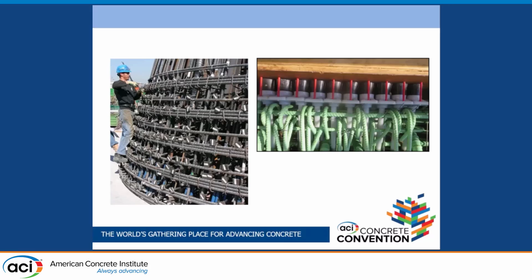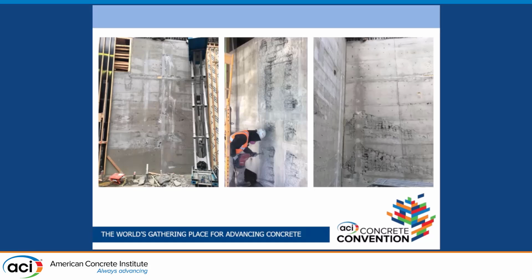Look at that. How are you going to deal with that amount of rebar congestion there? How are you going to place concrete here? This is going to almost be like a grout section. And then what happens when we build this? This is the way it looks. It doesn't matter how good you can consolidate that concrete.